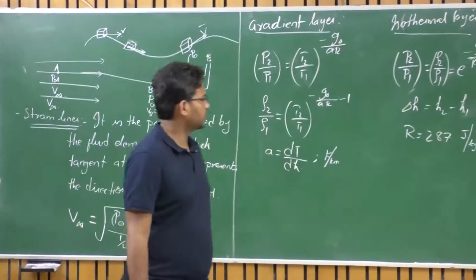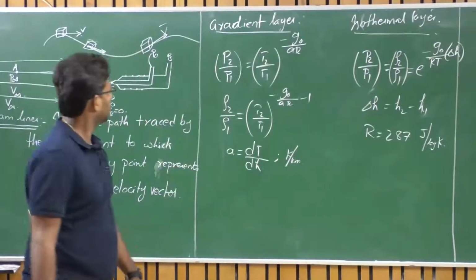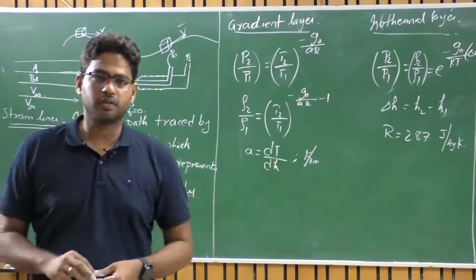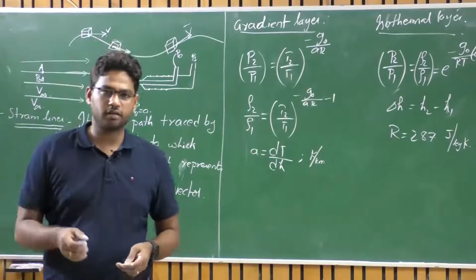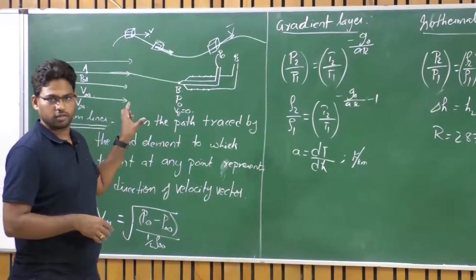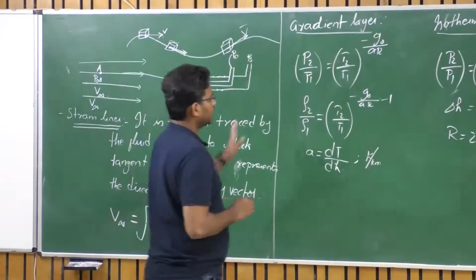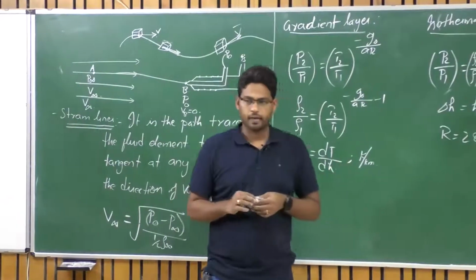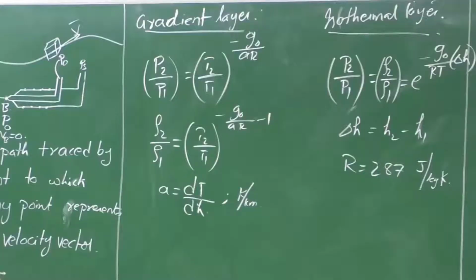So we have used these 2 equations and solved one example problem where we want to find the velocity of the aircraft at 12 kilometers altitude, where we are able to measure the total pressure. Is that what it is given, right? And we have solved using the geopotential altitude.